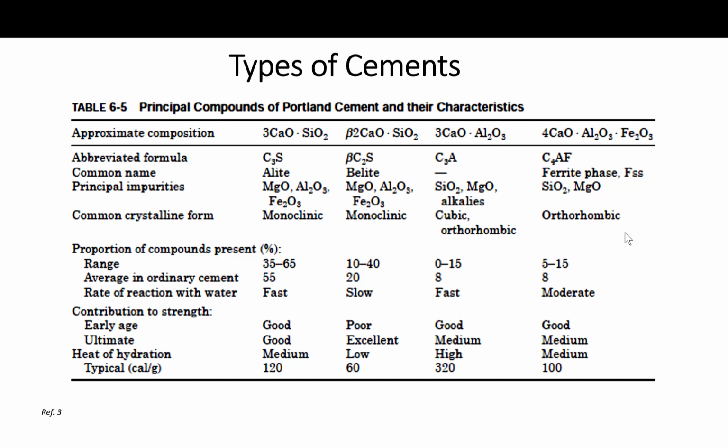because the fraction of each compound impacts the characteristics of the cement, and also to a certain extent the crystal structure. For example, for the C3A between the cubic and orthorhombic, there is a difference in hydration rate and various other properties, just for general information.